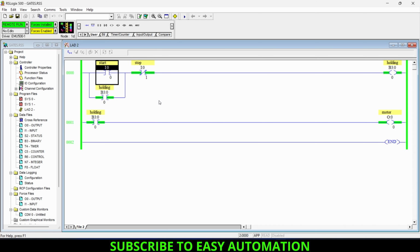But if I want to turn off this motor, I just need to toggle this another input. So by toggling this NC contact, our supply will break here and our holding will cut off here and our motor will stop here. And if I untoggle this one, then also our motor is off because the holding has cut off. But the main concept here I want to emphasize, that is bit memory.